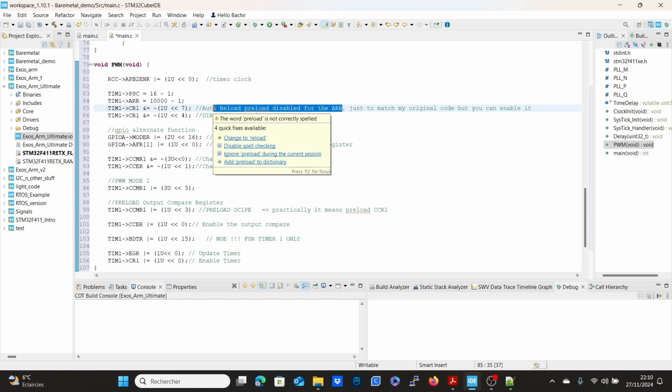So the thing is, the change is not going to be immediate. The counter was still incrementing in that old configuration, and it didn't finish what it was doing. And if you change that brutally like that, you may have some kind of unexpected behavior. So the interest with preloading is it protects things a little bit.